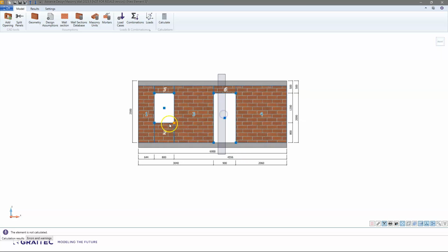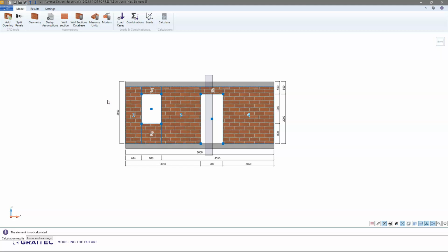And please notice that at this moment, it's very similar to what we've seen on advanced design. You have 3 design panels and also some that are not considered in the design, but the efforts are distributed to the neighboring panels. In advanced design, it was done using strips, so we integrated internal FEM forces into the integrated resultant forces, but right now we will simply just take the loading and distribute it on 3 design panels.